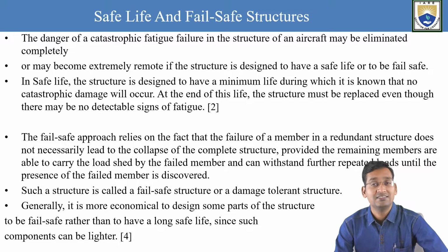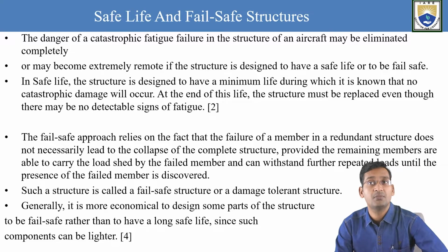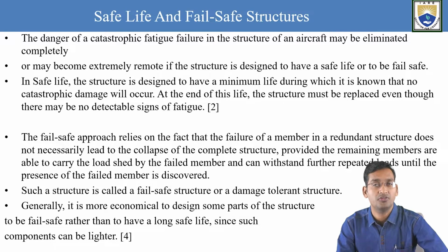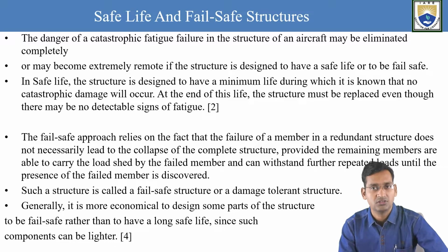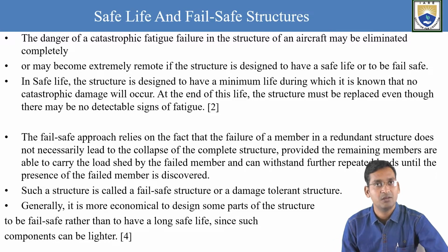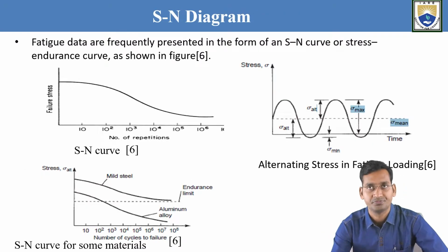Okay. Now generally it is more economical to design some parts of the structure to be fail-safe rather than to have a long safe life. Just like the example of the tire, right? If a puncture is there, there is no need to change the tire. You can just repair it. So it's not necessary that all parts have a long safe life. Some get punctured, you repair them and use them, right? So for those lighter parts, we can apply the fail-safe approach directly.